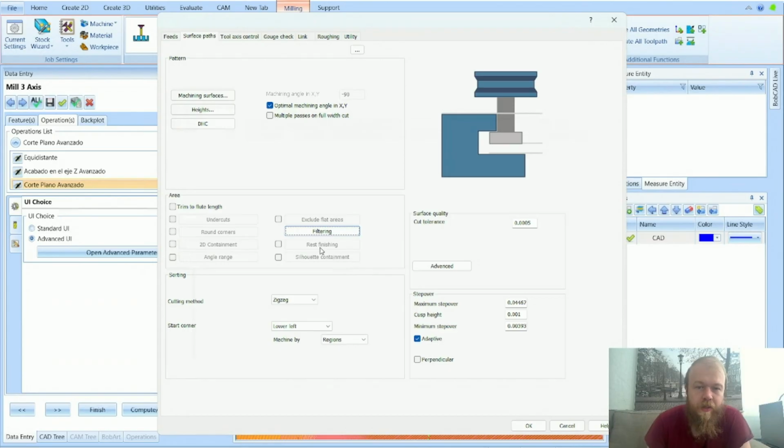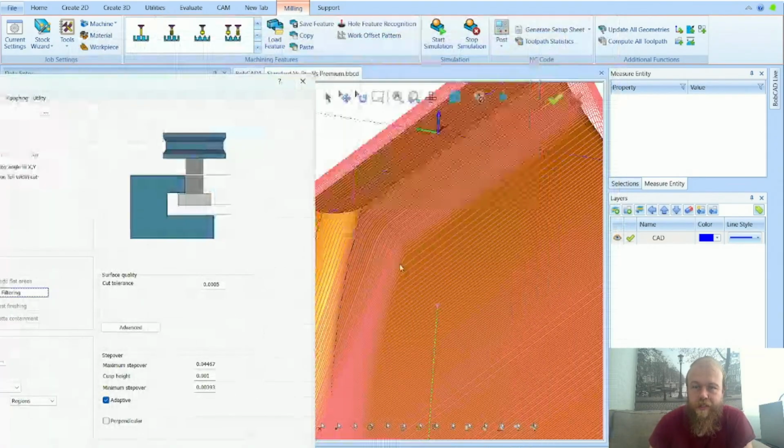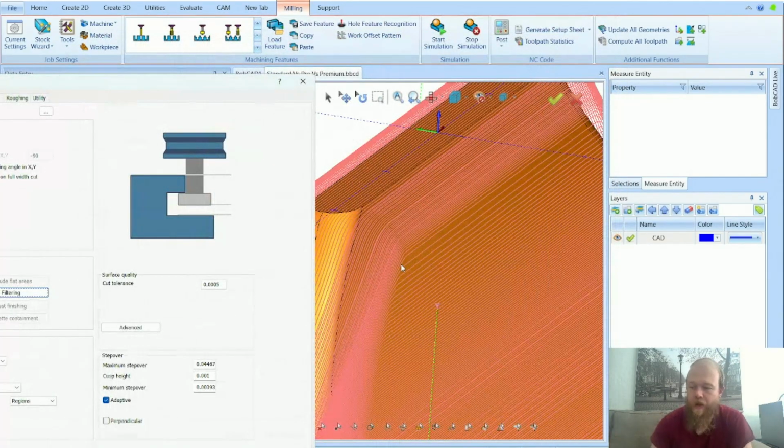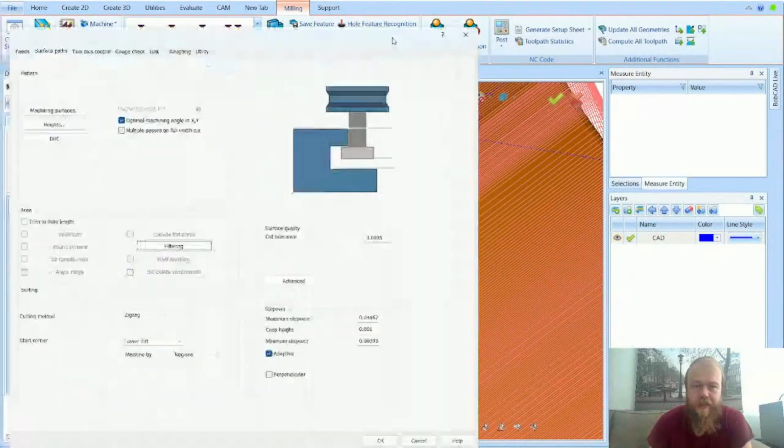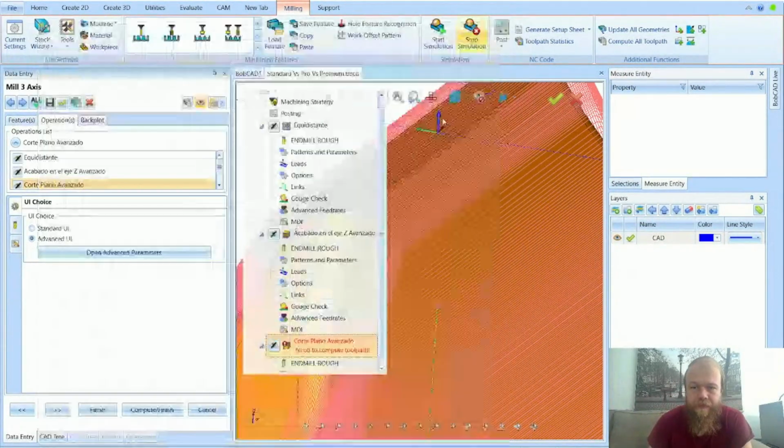I know in here in the roughing operations as well, you can set your tolerance levels, and you can also set arc fit, so it will fit an arc in any moves instead of line segments in these areas here, so that it will cut down on the G code, fitting arcs and making an arc move in the G code rather than point to point, and can cut down on the G code levels as well.